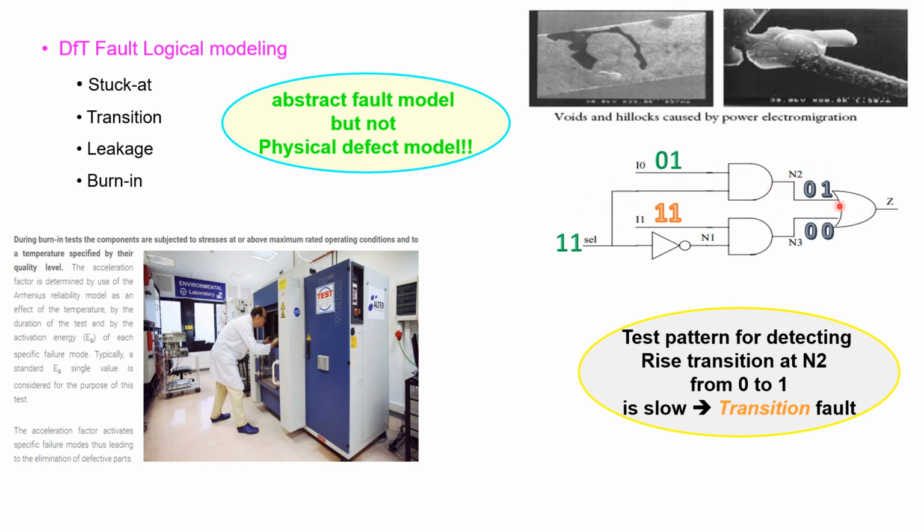So why we are figuring this out is because of electromigration, this interconnect metal layer may not be working as expected. The resistance might have increased. That means the void will be formed, not fully so that it became open, but it has become somewhat degraded. Because of that, the resistance of this conductor is increased, because assume that in this specific case the electrons have to move within this small distance.